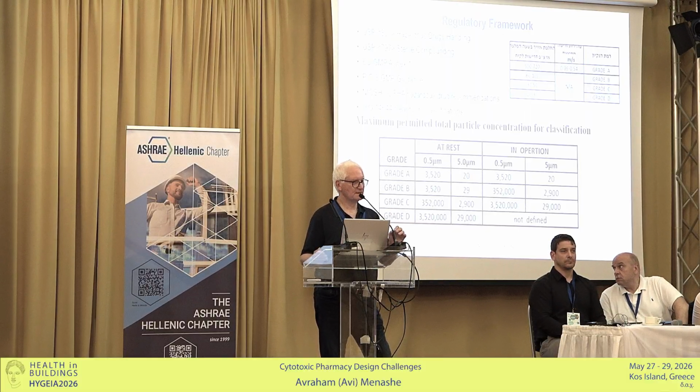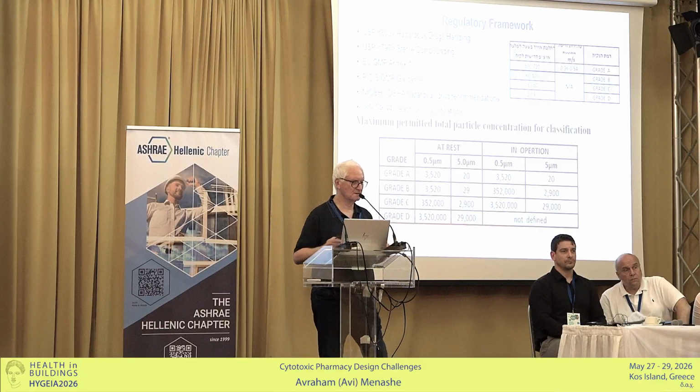So this is again a big challenge, to design a proper air handling unit that is able to overcome all the conditions. And conditions are variable because it's outside air, it varies between day and night. In some places in Israel, we can reach 80-85% humidity in the nighttime, and low temperature, or sometimes in another part of the country we have high humidity and high temperature. So it's again good engineering for us, and we know how to deal with that.